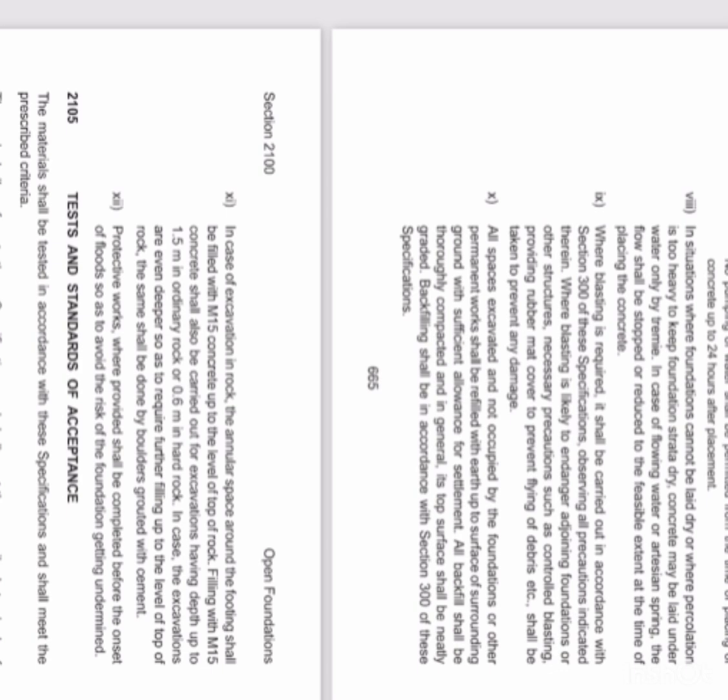All spaces excavated and not occupied by the foundation or other permanent work shall be refilled with earth up to the surface of surrounding ground with sufficient allowance for settlement. All backfill shall be thoroughly compacted and in general its top surface shall be neatly graded. Backfilling shall be in accordance with section 300 of the specification.